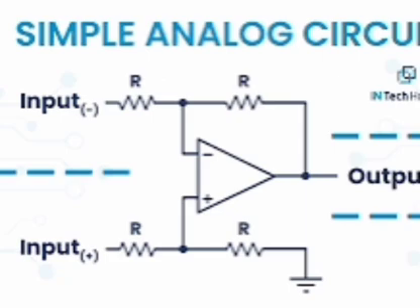DC load lines. DC load line is the locus of all possible operating points at which the BJT remains in the active region. If base current IB is less than IC sat by beta, then the transistor operates in the active region. If IB is greater than IC sat by beta, then it operates in the saturation region.